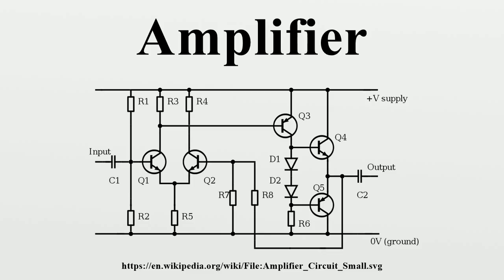Power amplifier circuits. Power amplifier circuits include the following types: vacuum tube (valve), hybrid or transistor power amplifiers, push-pull output or single-ended output stages. Vacuum tube amplifiers. According to Simmons, while semiconductor amplifiers have largely displaced valve amplifiers for low-power applications, valve amplifiers are much more cost-effective in high-power applications such as radar, countermeasures equipment, or communications equipment.